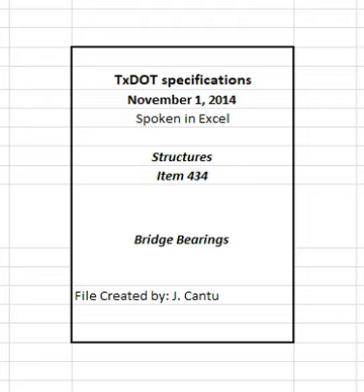Disc bearings. Consisting of a polyether urethane disc contained between upper and lower steel bearing plates. The bearing has a shear resisting mechanism to prevent relative horizontal movement of the bearing plates and transmit horizontal loads. Pot bearings. Consisting of a plain elastomeric disc confined by a shallow steel cylinder, pot, and a steel piston which engages the cylinder sufficiently to prevent their relative horizontal movement.